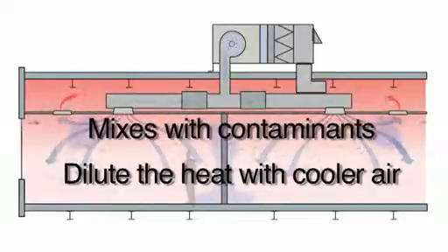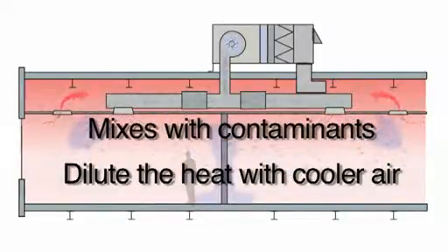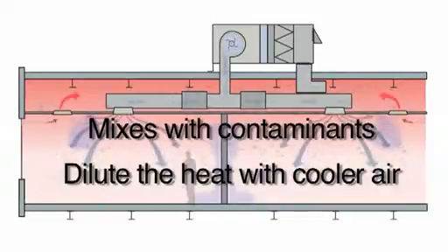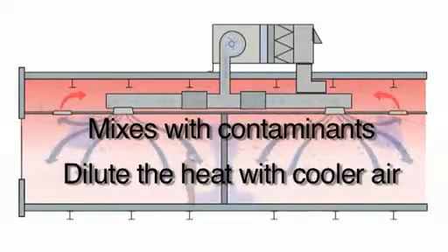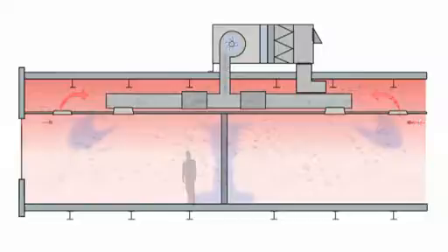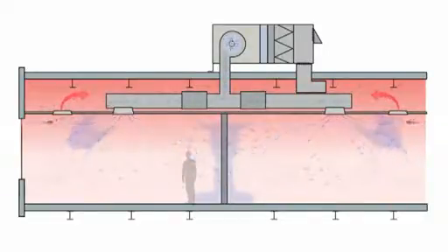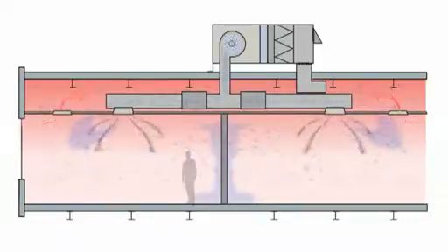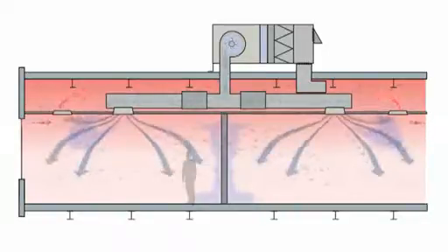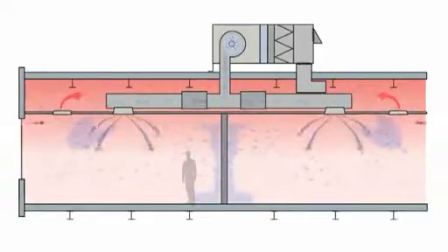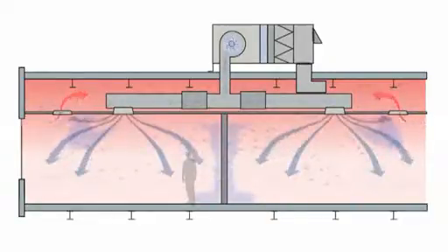The space air also contains contaminants, such as volatile organic compounds, or VOCs, from carpet, paint, adhesives, CO2, and skin cells from people, dust, dirt, pollen, and so on. The air provided for cooling is also filtered and provided with outdoor air so that the mixing of the overhead air into the existing warmer, contaminated air in the entire space allows the system to maintain the desired room temperature and a tolerable level of contaminants.